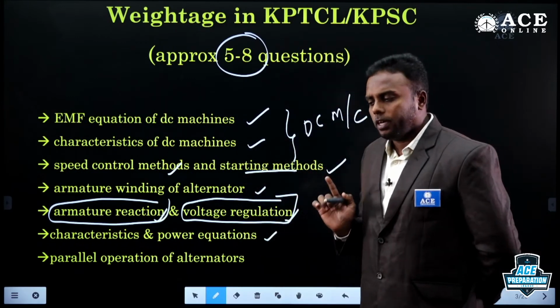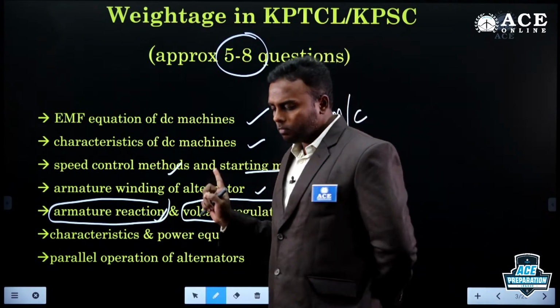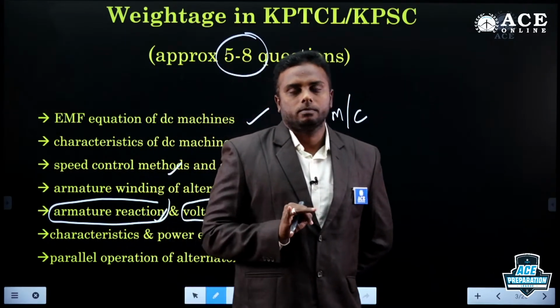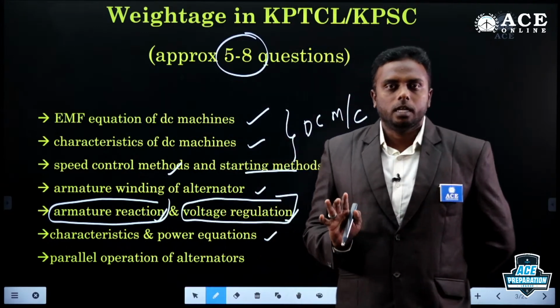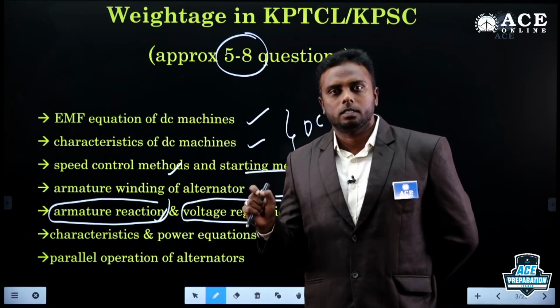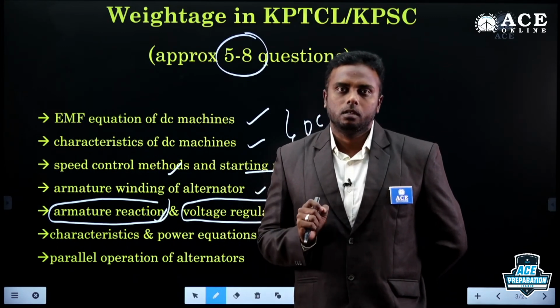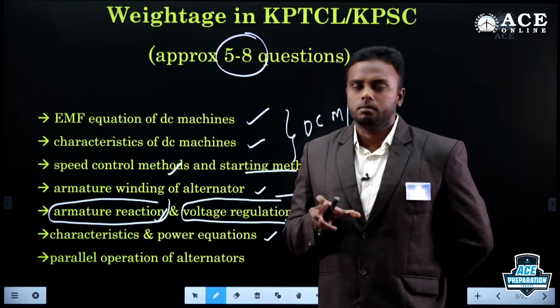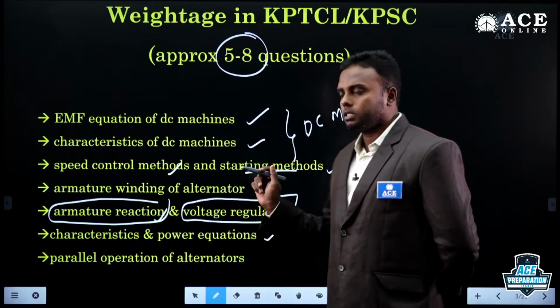Okay. So mainly the problem we get is, in synchronous or induction machines, we have three-phase power calculation and single-phase power calculation. So generally we make some mistakes while calculating three-phase powers, because while substituting line voltage or line current, you will get confused. So you need to concentrate a little on this power equation.